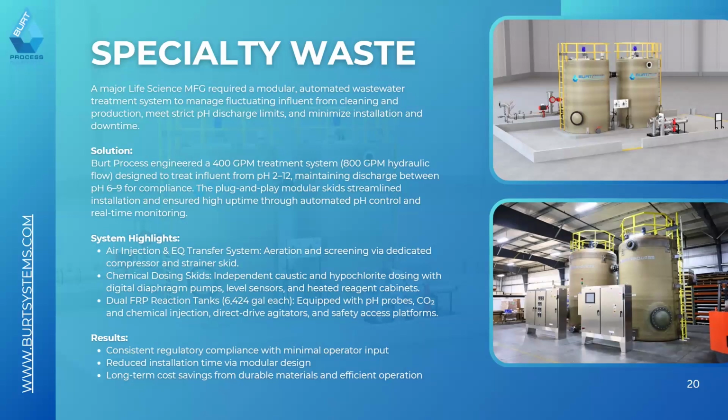Fiberglass is more common for some of the bigger systems, but fiberglass as a whole is not entirely better, quote unquote, than a thermoplastic. They have their pros and cons. Some of them are lower temperature. It really depends on the type of resin and corrosion barriers utilized as part of the fiberglass.